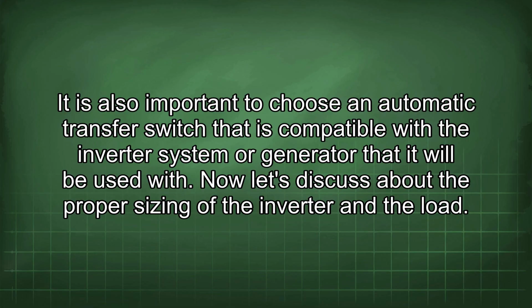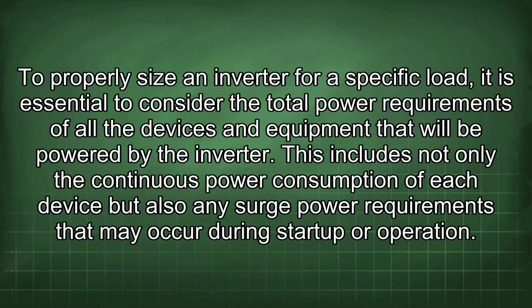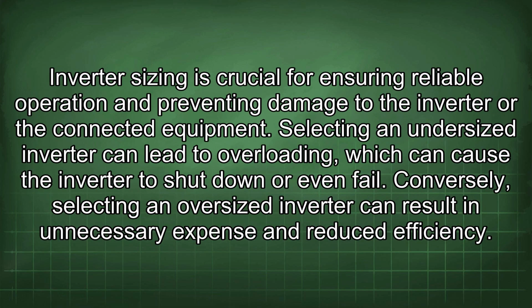Now let's discuss the proper sizing of the inverter and the load. To properly size an inverter for a specific load, it is essential to consider the total power requirements of all the devices and equipment that will be powered by the inverter. This includes not only the continuous power consumption of each device, but also any surge power requirements that may occur during startup or operation.